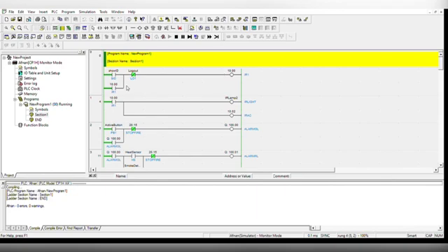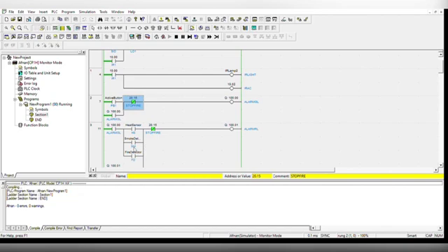First, we have the input for the first step, which is show ID and IR1, and the logout button is normally closed, which will make the output of IR1. The IR1 will give electricity to the light and to the air conditioner. The active button, PV1, will be normally open and the stop fire will be normally closed, which will have the output of alarm green light. Next, the alarm green light is normally open, and then we have the heat sensor, smoke detector, and fire detector. We also have a stop fire button, which is normally closed, and the alarm red light.